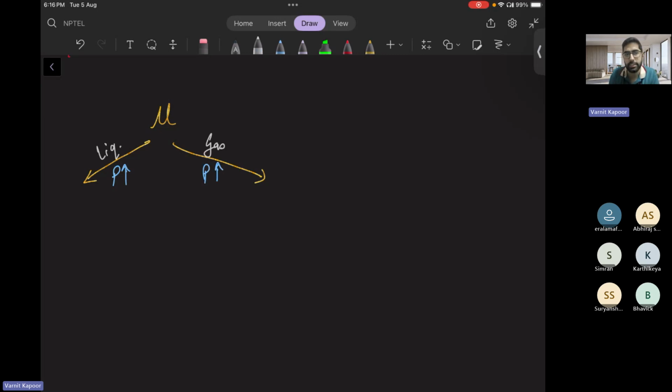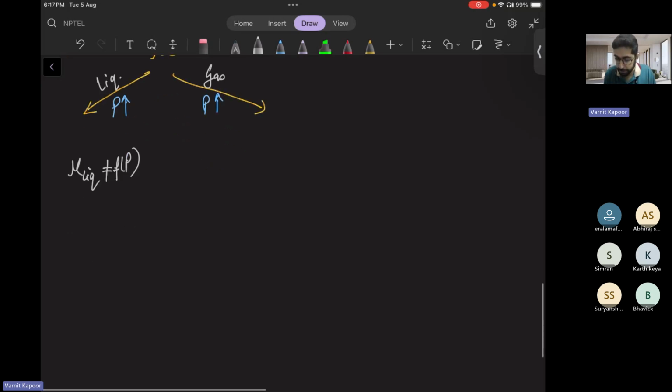I think liquid viscosity doesn't change. It is independent because there is no expression like P is equal to rho RT there. So mu of liquid is not a function of pressure, because liquid is generally incompressible in nature, where we will define a property called bulk modulus, and I'll explain that also. We have seen in the first tutorial that when you try to compress the liquid, it resists a lot, whereas a gas doesn't resist much. So it is more incompressible in nature.